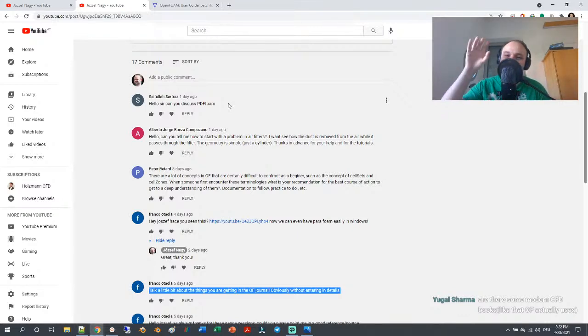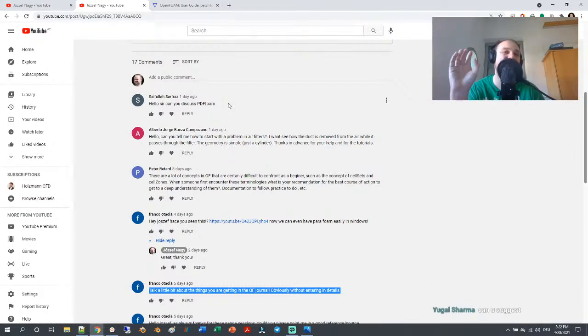So if you are interested in these two things, these are two things which more or less do the same, but not really. With cell sets and cell zones, you can select certain cells. You can do the same for faces or for nodes, so points. So it's just a selection of certain cells, and I think it's historical that you have two different types, because they are both really a kind of selection. But with cell zones you can do more, and most models which require cell zones or cell sets do use the cell zones.